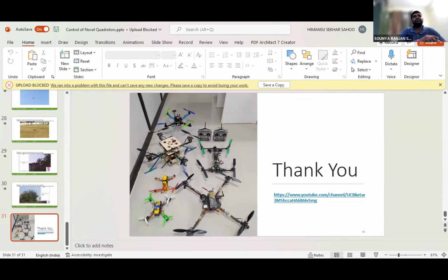We have found some conditions on the amount of force that the propeller should generate, so that it can actually flip, unlike variable pitch quad rotors or helicopters, where you can lose your attitude when you flip. That won't happen in such cases. In tilt cases, you can flip very smoothly, and you can transition through any attitude that you want. It can be a very smooth continuous transition.